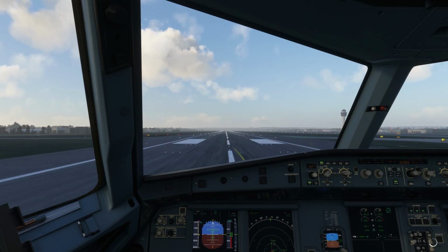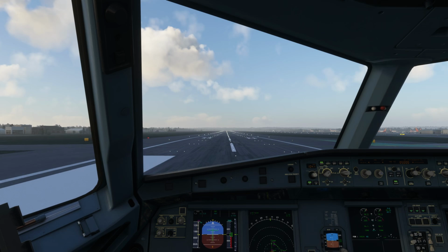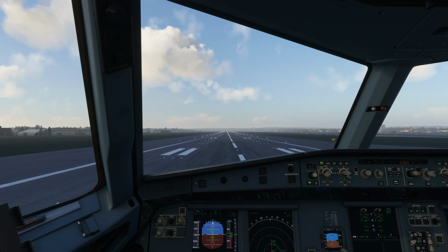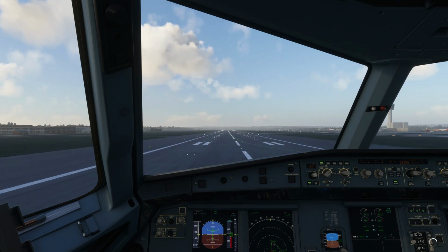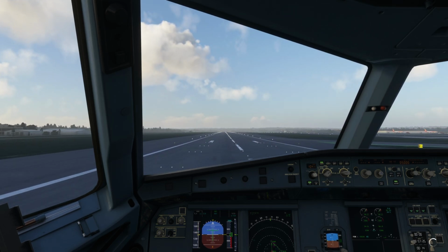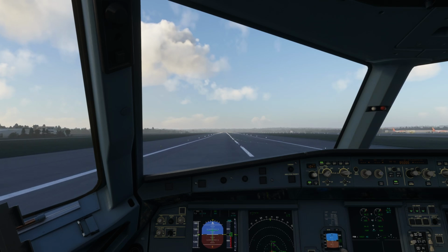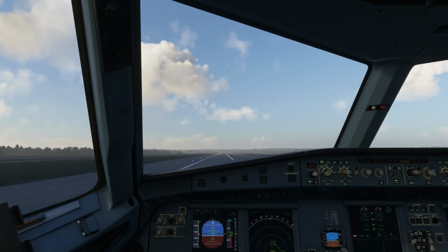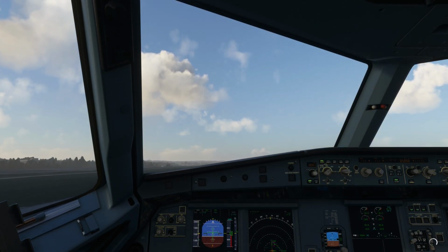Whilst my autopilot is not engaged, nav mode and auto throttle have been set, and I'll move my throttle to climb at about 1500 feet, which will allow auto throttle to engage, and the computers on board will control my airspeed. The Airbus 320 is a modern aircraft and designed to be flown on autopilot.